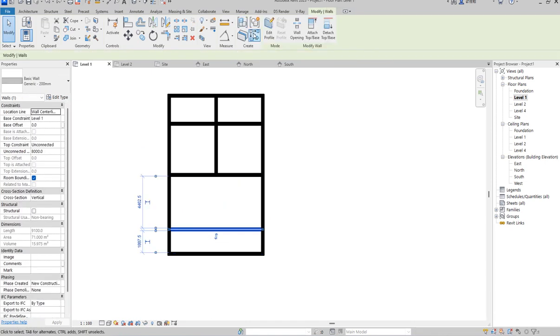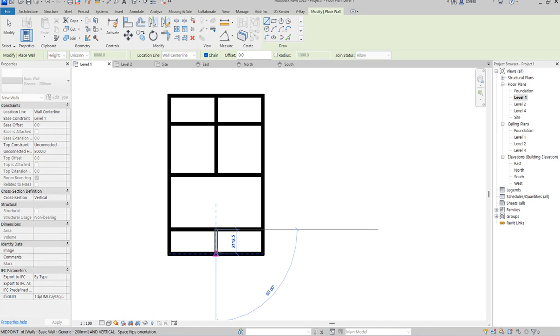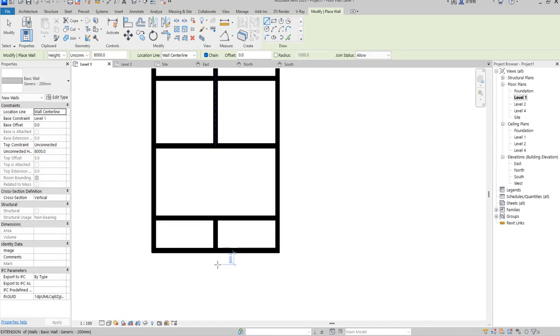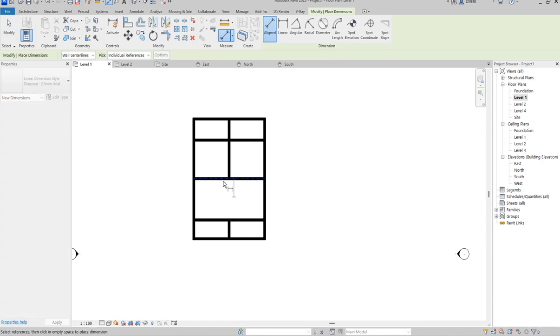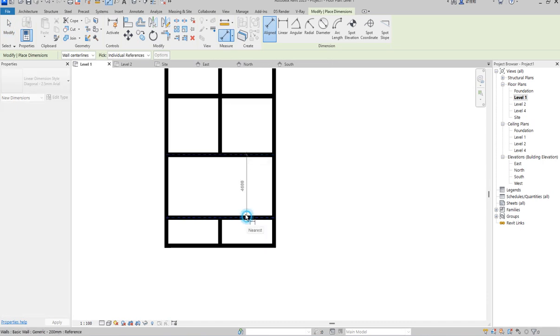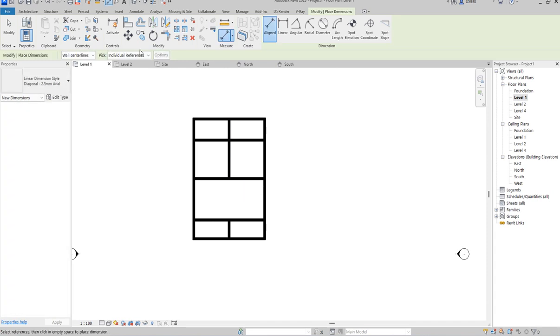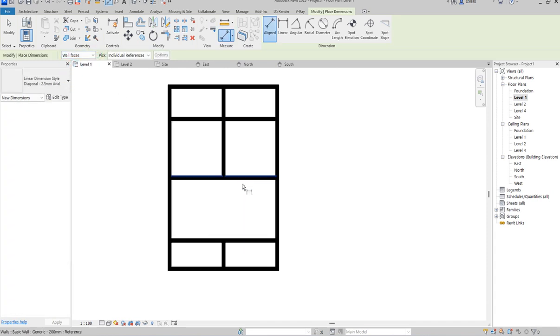and Control Z. So orientation of every program is going to involve that you will have some things you need to work with. So what have I done here? I need to look at the dimension and follow everything step after the other. So I want to check the dimension from here. What are the dimensions here? Now if you have issue with this dimension that's selecting from the middle, all you need to do is to change it from center line, change it to face,